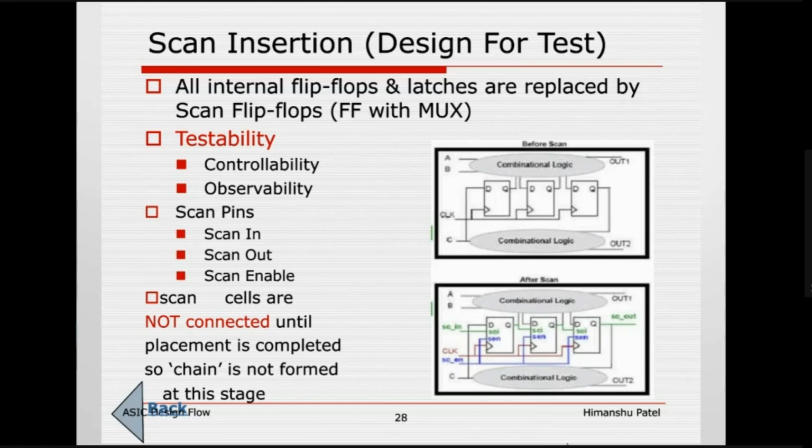Now, this scan input to the scan output we have created in a scan chain format. So you directly feed in, and all the combinational logic that is covered here, the tool can test at a time. So the tool will create the pattern, meaning the A, B, C value, right? It will give you, okay, the immediate logic of A, B, and C is going to the AND gate and OR gate here. There is an AND gate here, and there is an OR gate here. Likewise, this is calculated by the tool, which gives a pattern.